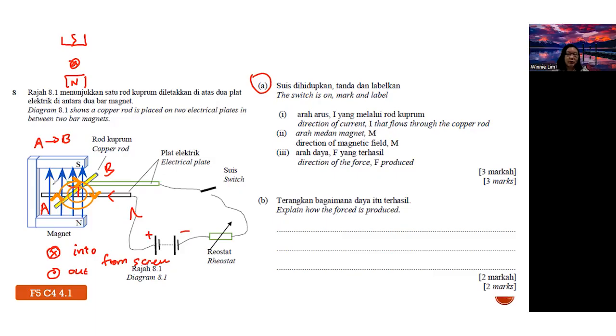So if you combine these fields, on the left side, you look at the arrowheads, they are upward. But on the other side, it seems opposite already. So they will combine and produce an uneven field, something like this. If I redraw again, this is south, this is north, then this is into. After you combine, you will have more field on this side. This is called the catapult field.